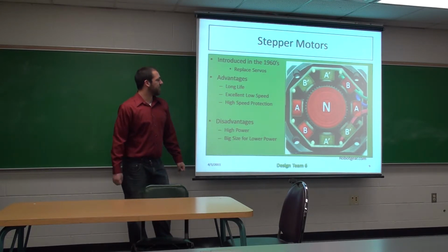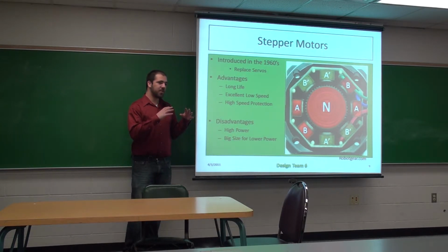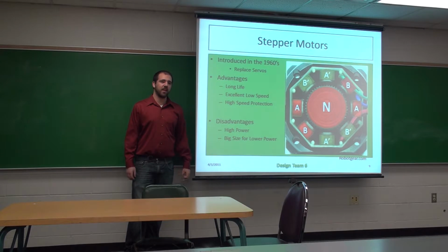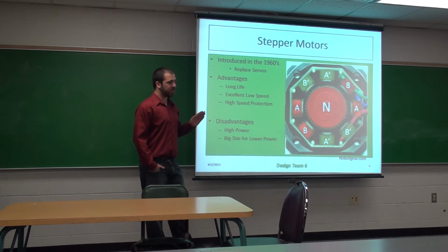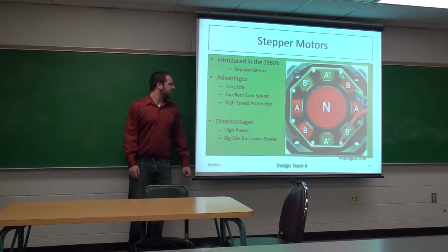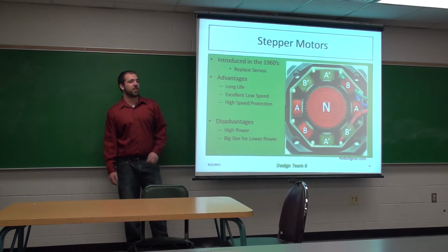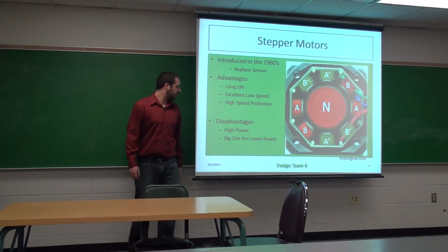The advantages to this are very long life because the rotor and the stator aren't touching each other, which means there's not going to be any mechanical wear. Also, it has excellent low speed because you're only moving one step at a time. You don't have to send it just a voltage and tell it to run. You're going to make it only go one step at a time every time. You also have high speed protection because once you start making it go too fast, the absolute worst that's going to happen is it's going to seize up and do nothing, but there's not going to be any mechanical wear on it.